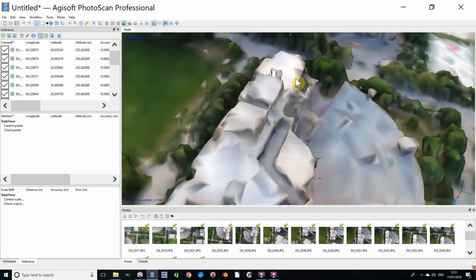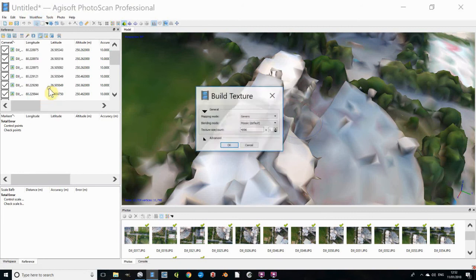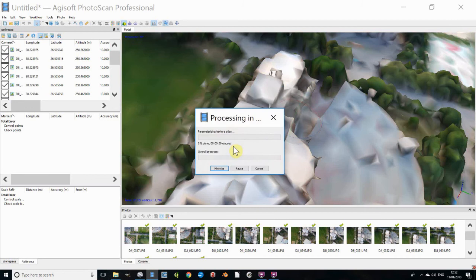Of course, now we can improve this. We can produce things that are good for visual display, and those are called image textures. So just go with the defaults. This can be known as image draping. In the beginnings of GIS, it was very popular to have a DEM and drape an image over it. It's going to mold the images onto this 3D surface that we're now looking at, and that will add much more detail to the visual aspect of it. This process is usually quite fast. I'm hoping that I won't have to stop the recording for this.